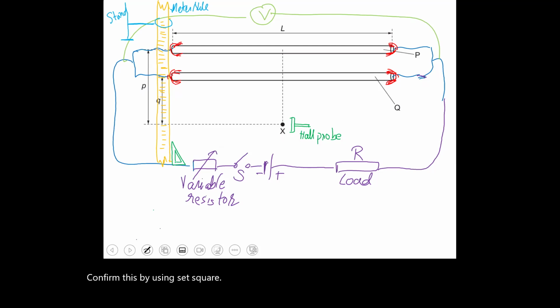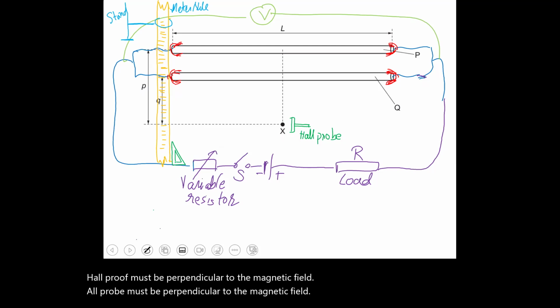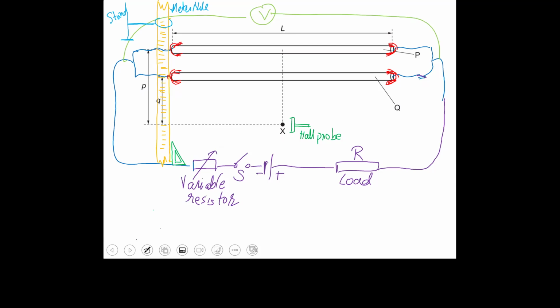Hall probe must be perpendicular to the magnetic field. Hall probe must be calibrated before use.